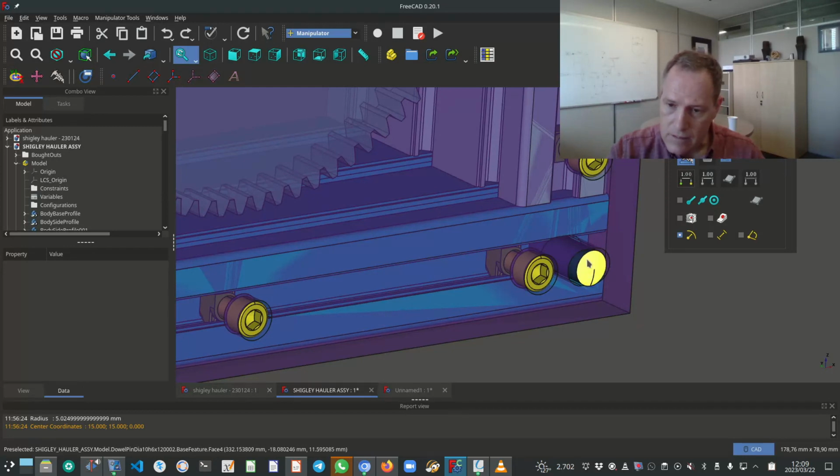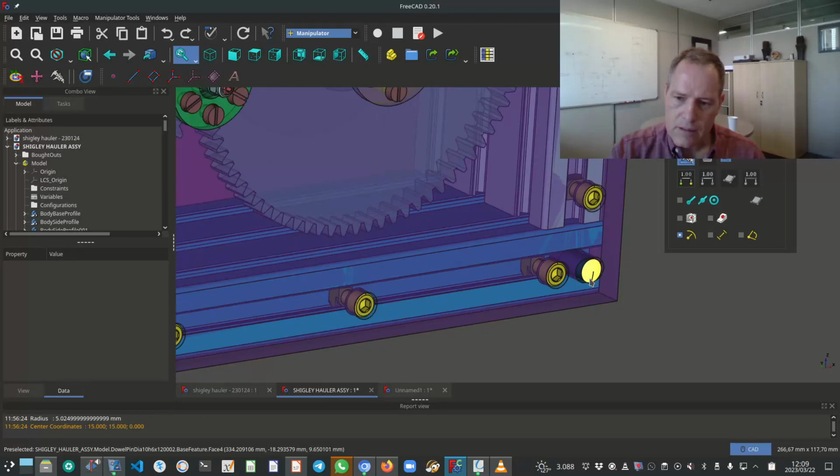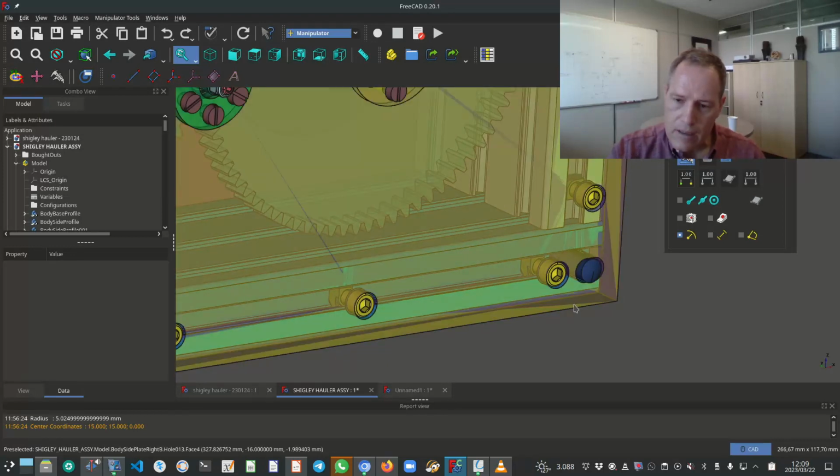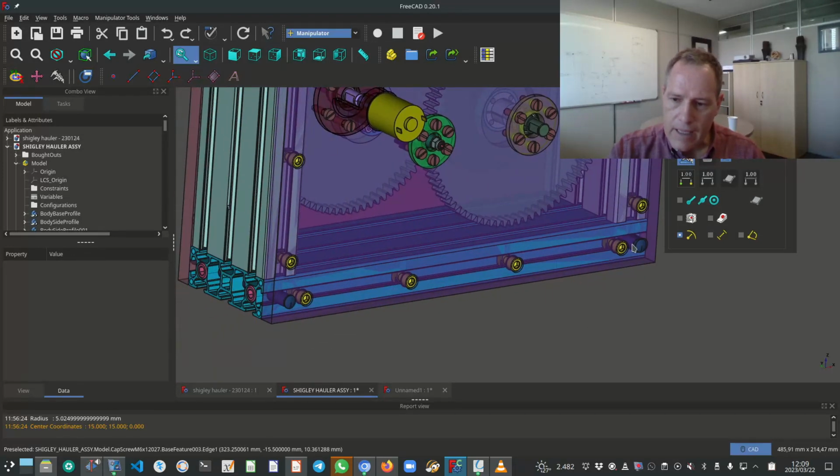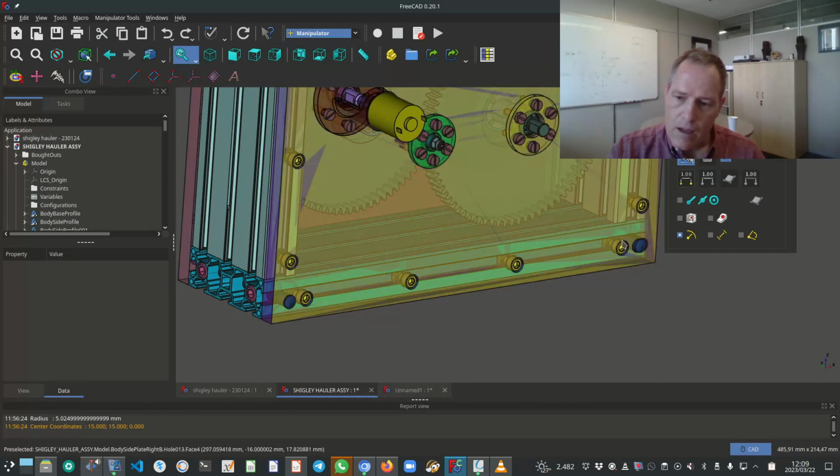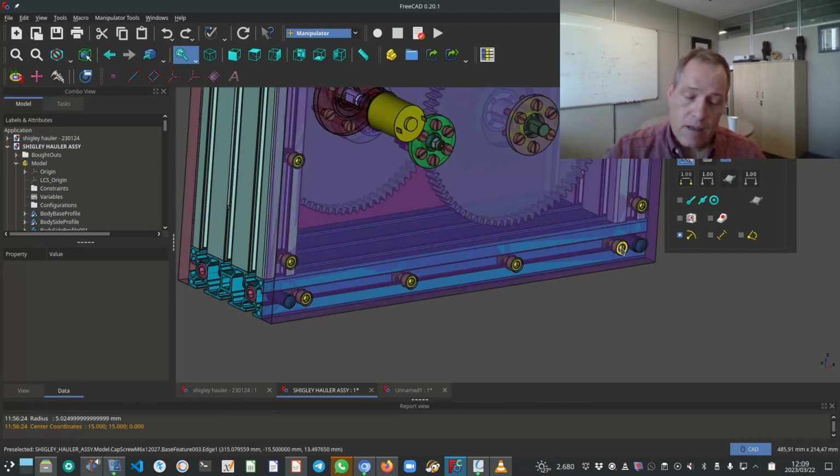The width of the slot is very accurate, but the length of the slot can accommodate variance in the distance between the 2 dowels in the base plate. So that's something important for you to note.